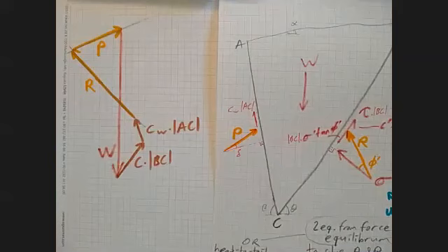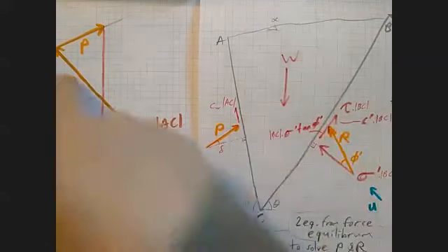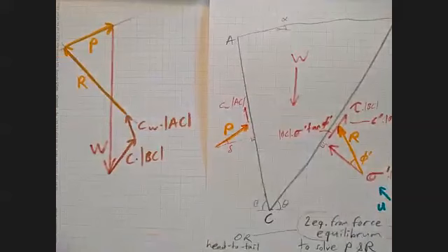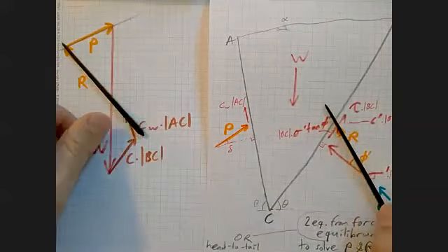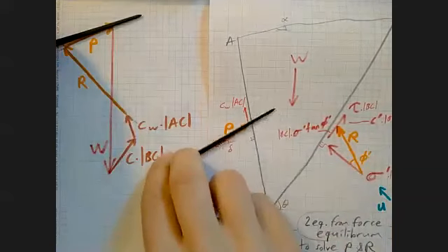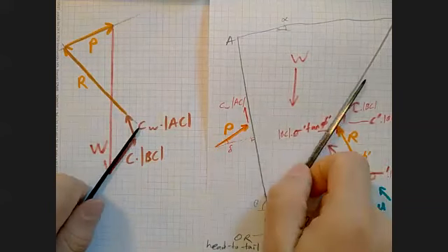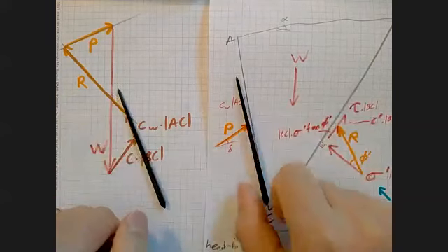Here it is. So you take this orientation, replicate it here. You take this orientation, replicate it here. And then once you figure out the intersection point, you figure out the lengths. So this is parallel to this, and this is parallel to this. And of course, these are also replicating these forces. This is parallel to this. This is this force here, etc.